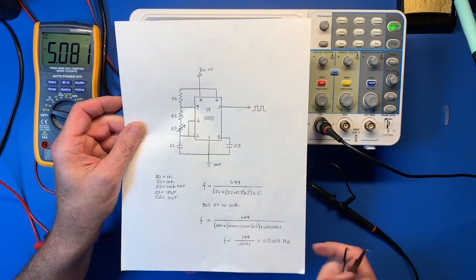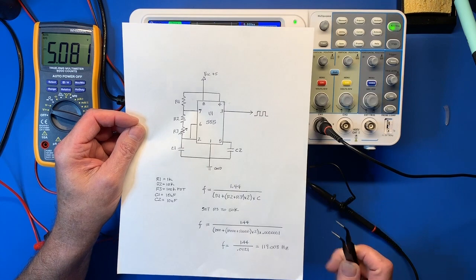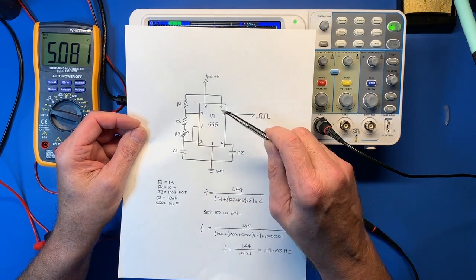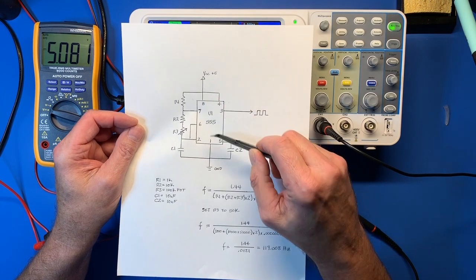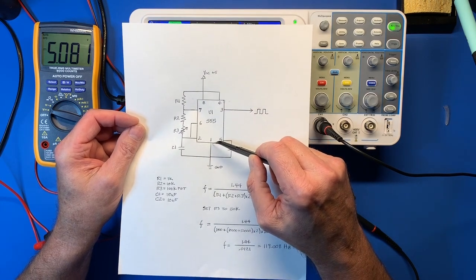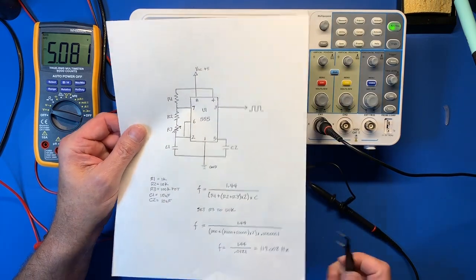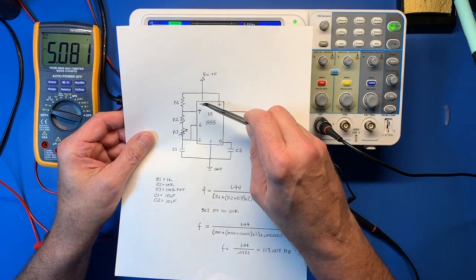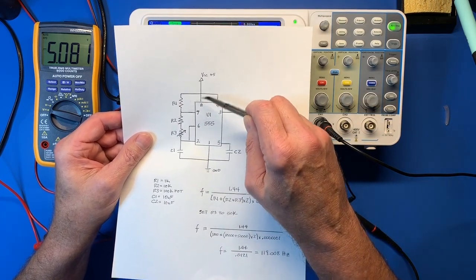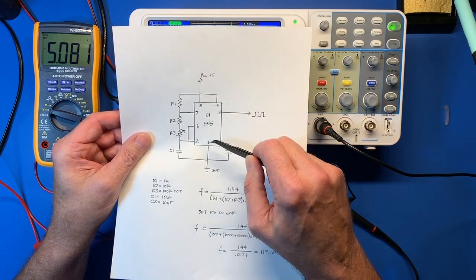I realized, however, that I missed a major component. We need a capacitor from pin 8, the 5 volt pin, to pin 1 or ground, as close to the chip as possible. Now why? We need that for that very reason, because as current is drawn in these long leads, you have parasitic capacitance and you have deviation in the potential between 8 and 1.